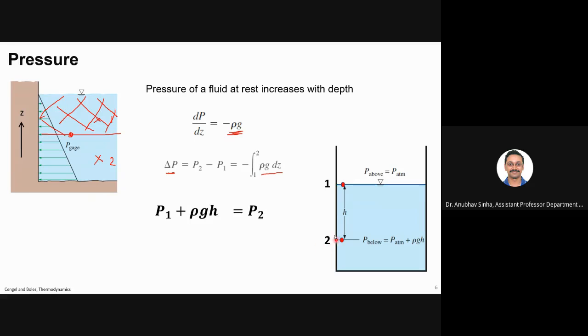Now suppose I know pressure at point 2 and want to calculate pressure at point 1. Now I am going up, so P2 minus rho gh will be P1. You will see numericals where you have to come down or go up, so accordingly you will calculate how the pressure is changing. Is this clear, how I have these last 2 equations? Yes, sir, it's clear. Fine.